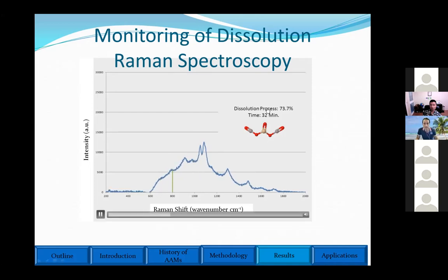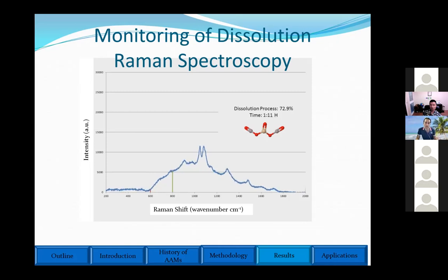And then I monitored it for 24 hours to see what's going on inside the concrete when I introduce the chemicals over time. And then I could get the exact timing and mixing procedure for any specific type of precursor. For example, if we have powders, waste material like AES fly ash, with high impurities, with some components that I don't like.